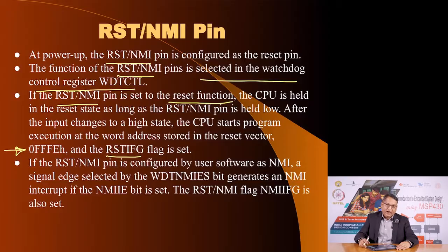If on the other hand this pin has been configured through software as a NMI, then a single edge selected by this register generates a NMI non-maskable interrupt, and it will go to the vector for non-maskable interrupt and execute a program in response to it.